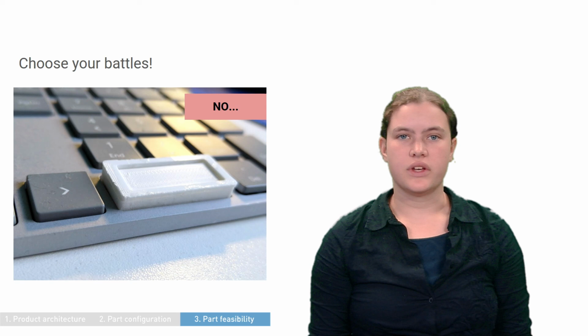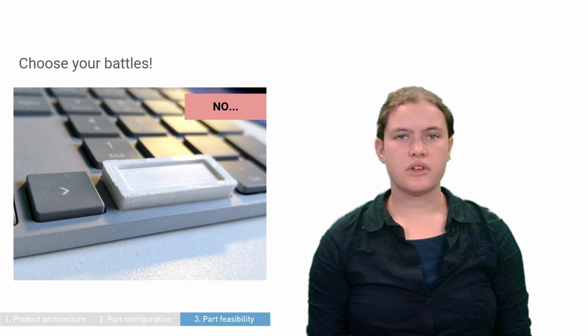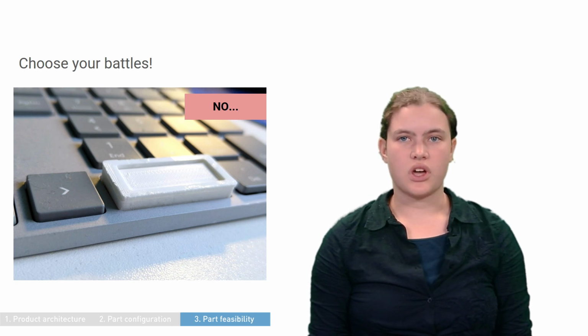The keyboard, on the other hand, was not a success. The original part was a metal hook with measurements smaller than 0.5 millimeters. This made the redesign very challenging. After 35 hours of work, there was still no favorable result. Therefore, you should choose your battles. Not all parts are feasible for 3D printing, and some are, but take too much time and effort.